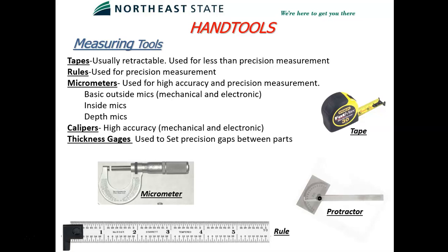little silver hook tip on the end of a tape measure, it moves back and forth, and it's supposed to do that, and the reason is that it moves so you can do inside and outside measurements. So it typically moves the thickness of that metal clip on the end. So that's the thickness that it should move. And so when you butt it up against something, it should move in. And then when you hook it on something and pull out, then it'll go out to do an outside measurement.